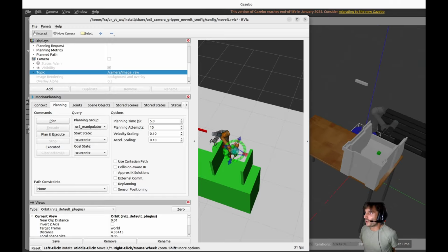There we go. So the robot reaches the target position by considering the wall of the bin that we have hard-coded as a collision object, and the motion planning plugin of MoveIt planned the trajectory of our robot, or better, the end effector, accordingly without colliding with the object.